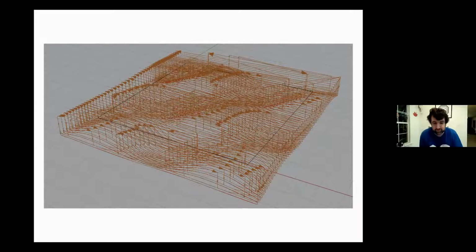The forces involved are quite high. So what you need to do if you're cutting down is, instead of just going along your path, you need to create a set of levels that you cut out first. So when you come to make your final cut, you're not removing that much material.